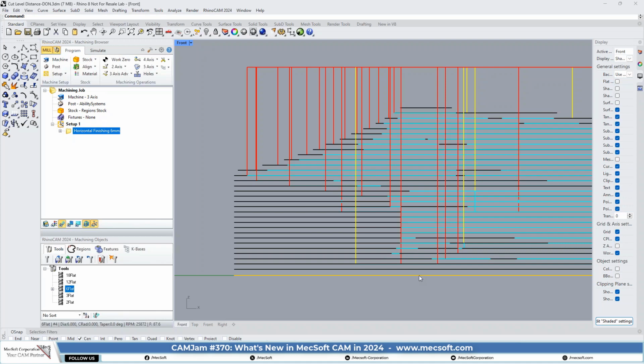Okay. But now with this option, if you specify exact cut levels, what will happen in those situations? In those situations, yeah, you're not going to get a cut level at the bottom. So it'll just be left out. So you'd have to enable clear flats in order to get one at the bottom if it's a flat? Well, yeah. Usually you would use the other option. You would just uncheck this option, and it'll use the 2023 default behavior. And if that was working for you, then just continue using it. Do not use this option.